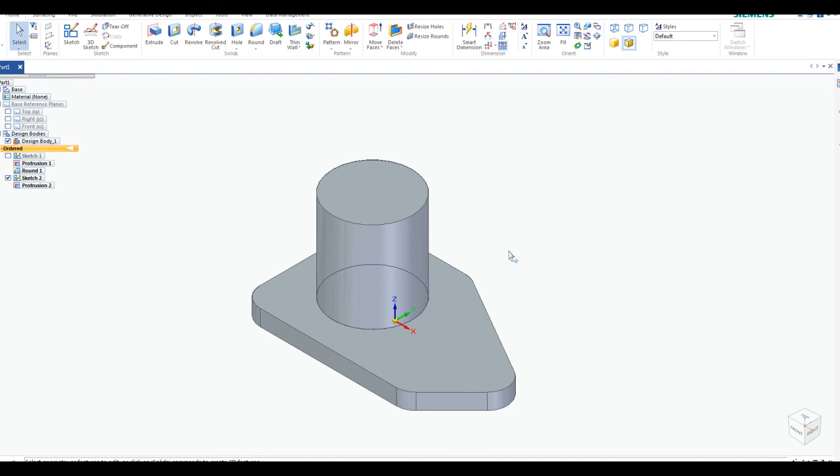All right, there's one more main extrusion, and that is the protrusion that comes up against the side of the cylindrical boss. We are going to use a work plane or a parallel plane to actually position this. So here's how we're going to do it. I'm going to first of all rotate it using this corner of my view cube so I can see the back.